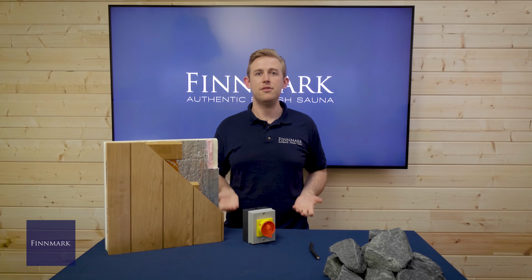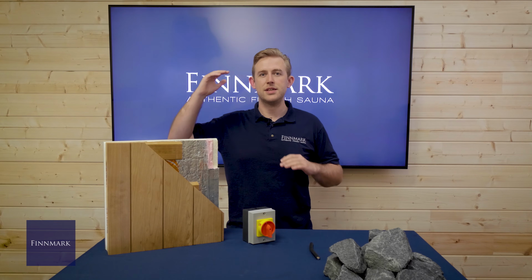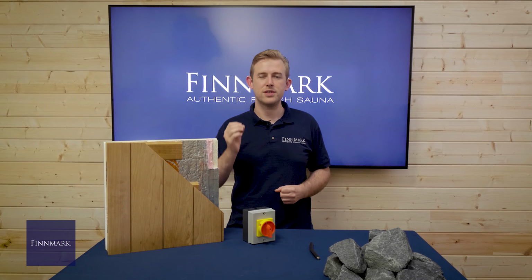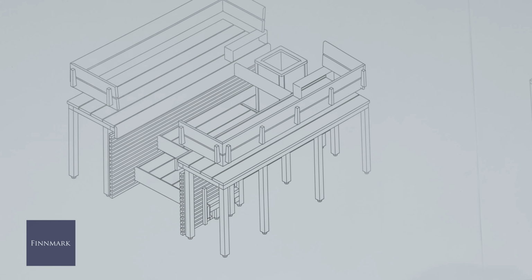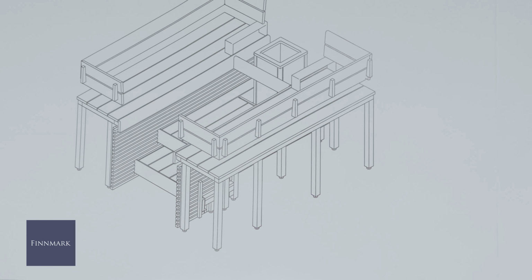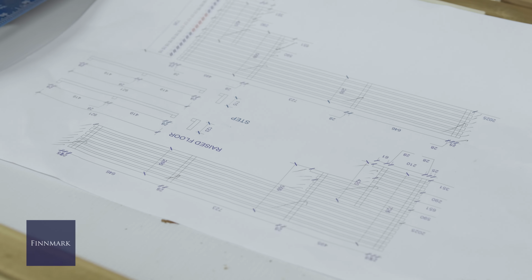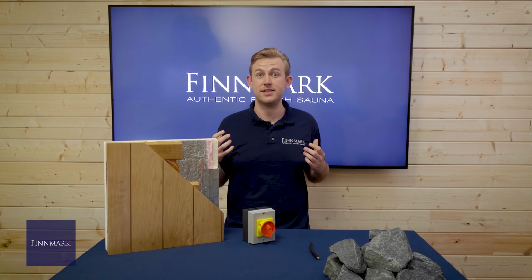As we all know, heat rises and all the heat and steam generated in the space will sit up in the top half of the sauna. Even with good ventilation, there will still be temperature stratification across the space. No sauna, even if on for hours, will become an isotherm. For that reason, Finns design their saunas with an emphasis on maximising the upper bench space as much as possible. This is where, given the choice, the users will spend 95% of their time.